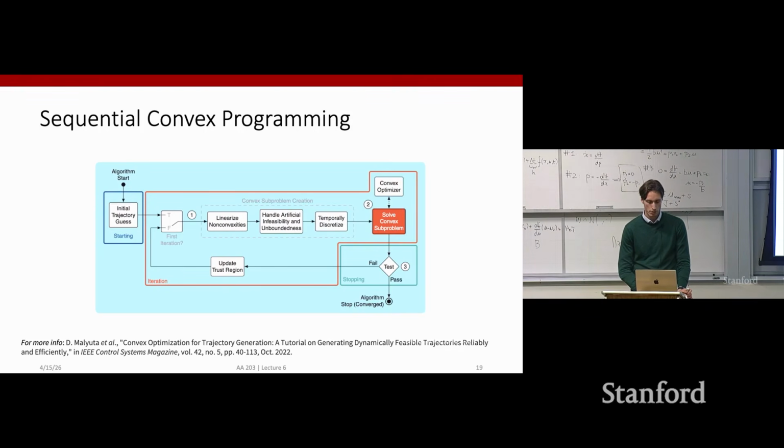And so now to conclude, if you were seeing those s variables before, this was indeed the slack variable. We are introducing this fictitious optimization variable s, which we are adding to our bound constraints on u, and in the cost, so we are penalizing the slack variable. If you look at the results of the optimization, we see how the slack variable decreases over time. Initially, apparently it is helpful to violate some of the constraints, but since we're penalizing them, this reduces and ultimately goes to 0.